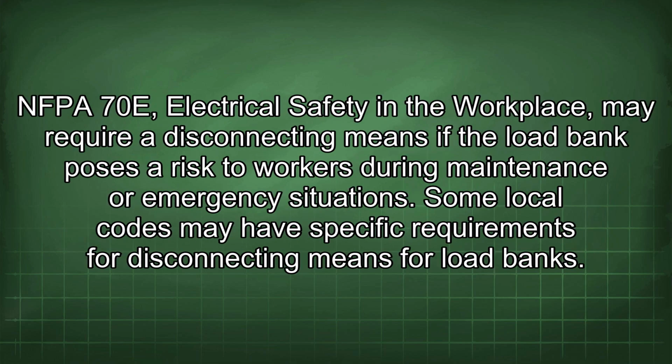NFPA 70E, electrical safety in the workplace, may require a disconnecting means if the load bank poses a risk to workers during maintenance or emergency situations. Some local codes may have specific requirements for disconnecting means for load banks.